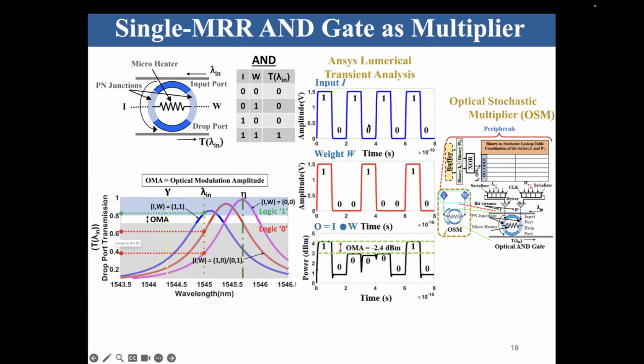We discussed that earlier. One way we thought of doing that was a simple lookup table based design. The binary operand is accessed from memory, and the lookup table gives us the stochastic conversion of those operands. That would be parallel, of course, and then you use serializers to feed those stochastic operands into the microring, and then you can achieve a multiplier.